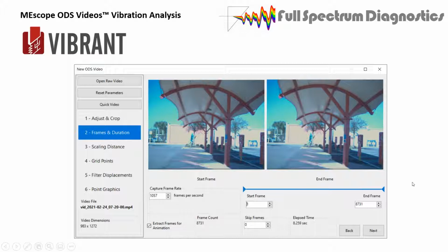In this video, there's some low frequency stuff. I'm going out and I'm actually hitting the structure and triggering the vibration. So I have to have a nice chunk of time, and the buffer is 8 seconds long. So I am processing the entire 8 seconds, which might take a few minutes to do. But anyway, I just want to unload the entire buffer so I can see the impact, I can see the ring down, and I can always clip it out afterwards if there's something in there that I don't need.